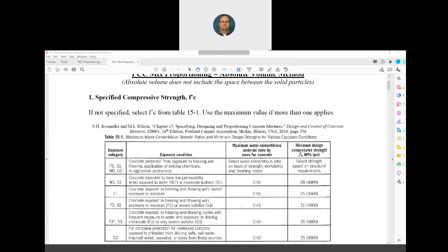Moderate sulfates: remember, the sulfate chemical SO4 will actually deteriorate concrete. In our clay soils here in Green Bay, we actually have moderate sulfates. Because of the Leo Frigo Bridge failure, which was part of that, we would test our soil to make sure we have moderate sulfates. Typically this tells us what kind of cement to use too, which is Type 2, moderate sulfate. So if we have moderate sulfates, which we do in Green Bay, and need low permeability, such as a basement wall, yes.